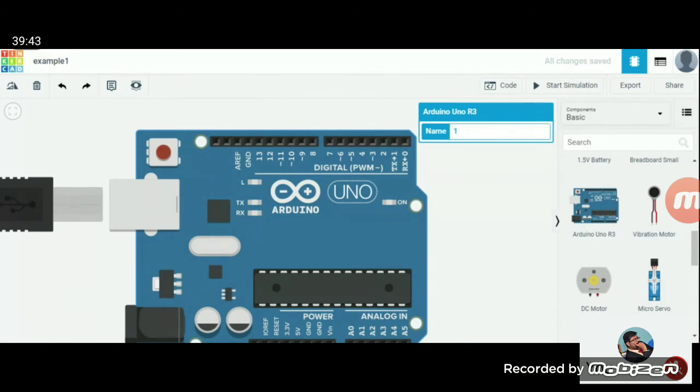While doing your projects, you will be using switches, MOSFET or IGBT, whichever is your choice. Microcontroller outputs are not sufficient to drive those switches, so you have to use a driver IR2110 to drive them. Here we won't be using 0 and 1.